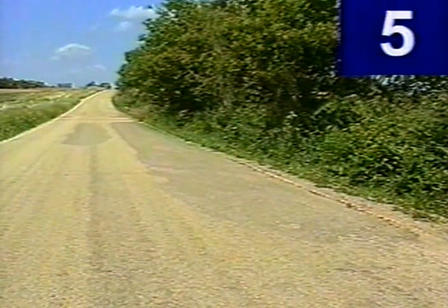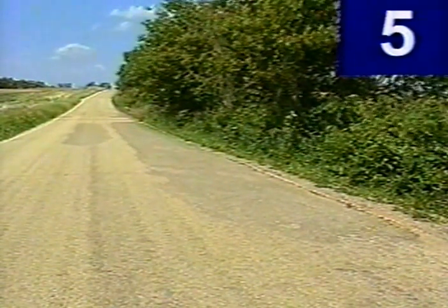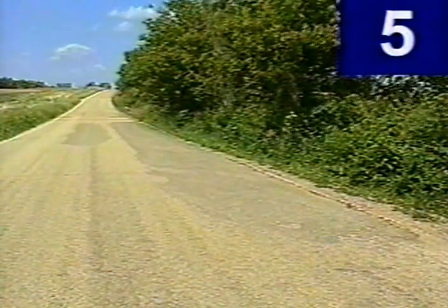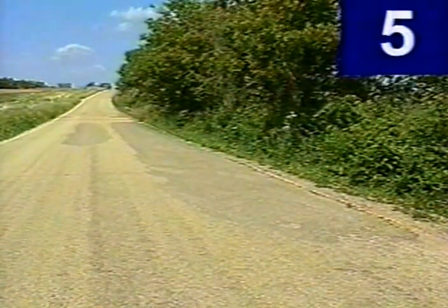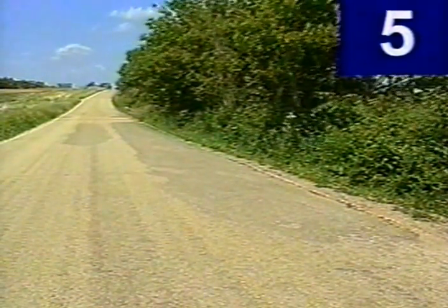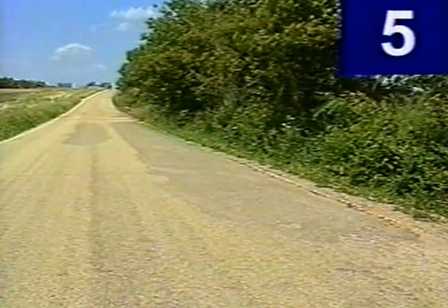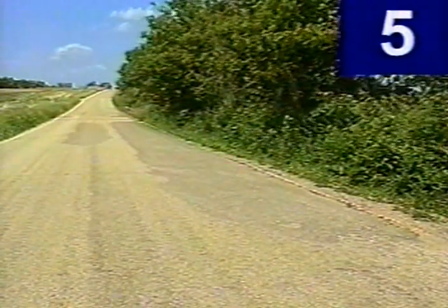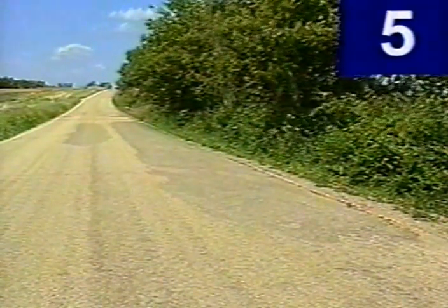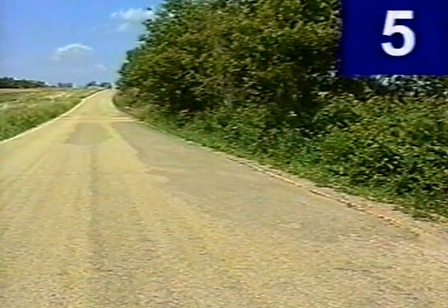Here you have a pavement that has been wedged, and this wedging is doing very well. While there was perhaps some surface distress or some cracking along the edge, they patched it, and it's holding up very well. Inherently, this pavement looks sound to me. I would consider it also a good candidate for a surface treatment such as a seal coat.